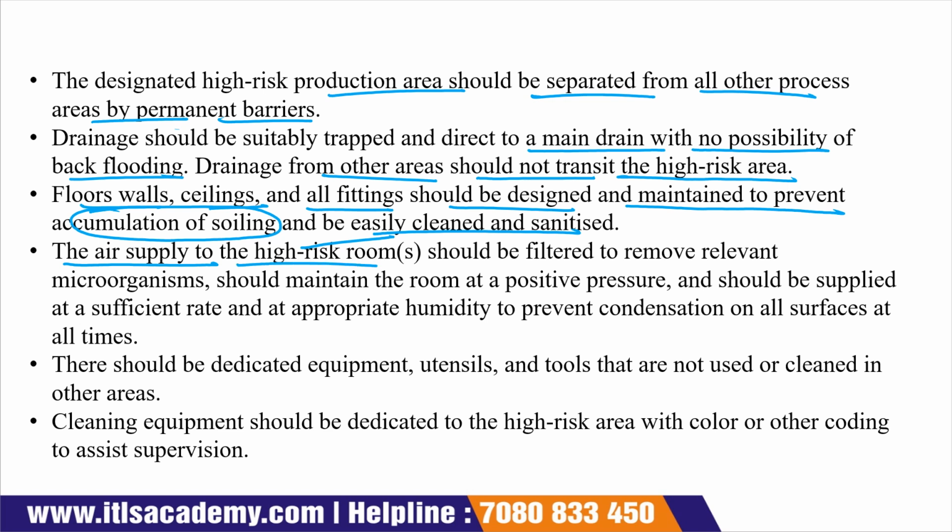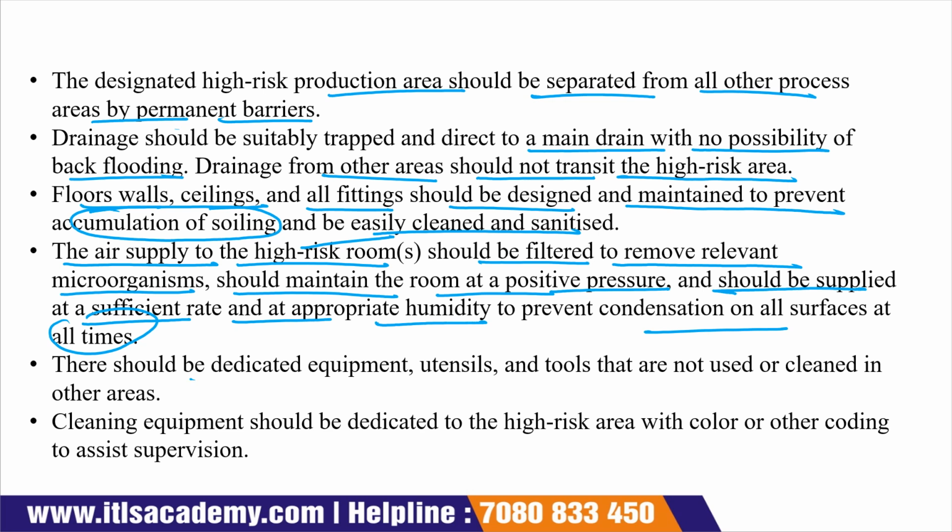The air supply to the high risk room should be filtered so that it removes relevant types of microorganisms, and the room should be maintained at a positive pressure, with air supplied at a sufficient rate and at appropriate humidity so that it prevents condensation on all types of surfaces at all times. There should be dedicated equipment, utensils and tools used in that area. They are properly cleaned and should not be used in other areas.